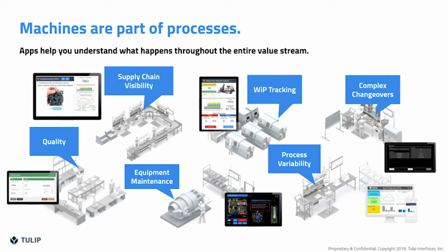What that allows is for the process engineers to turn around and see that 3/4 of the way through the shift on a consistent basis, they're waiting on material to come from the warehouse, or there's a 20-minute tool changeover every 10 pieces. They can look at where the strengths of their process are and where the weak points are. And when they know what the weak points are, they can start seeing how they can close those gaps and improve overall equipment efficiency. As well, with Tulip, it's not just OEE, it's OPE, because you're gathering that human element and capturing what's going on with the operator as well, not just the machine.